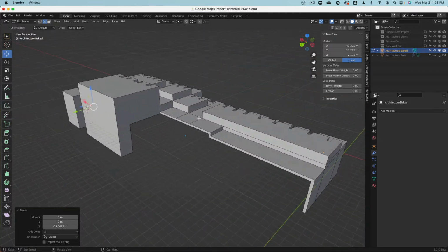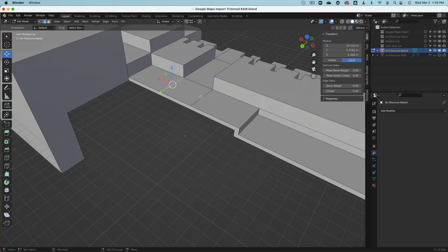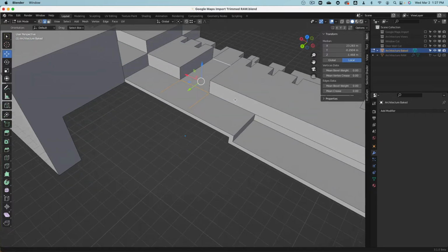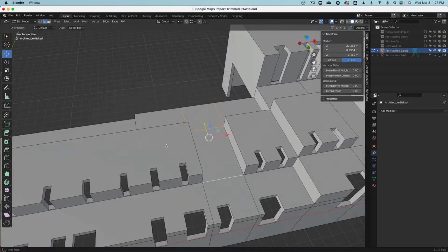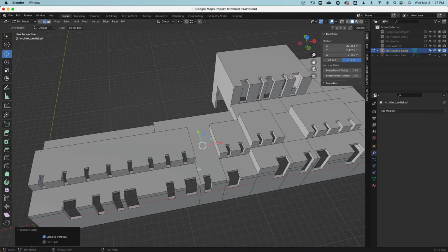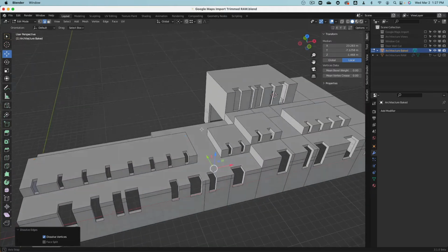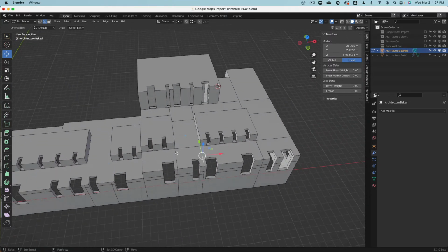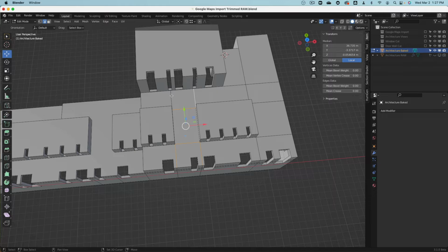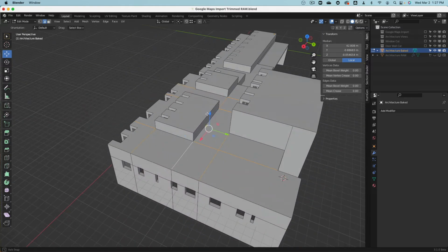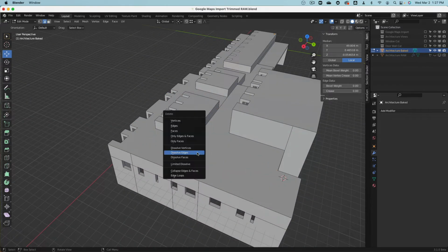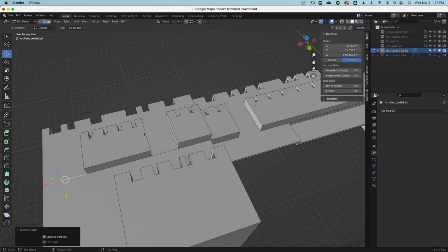So this is also all quickly what I wanted to show you, just so you see how this command worked. With the Boolean command, sometimes you can have issues, and you might have to trick around a little bit, and then I see here, it needs these edges to connect this.